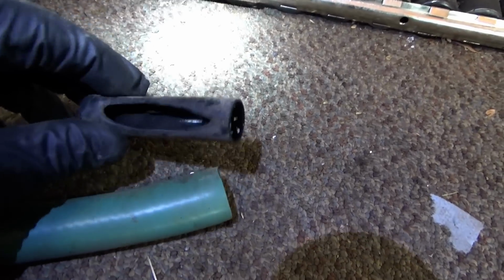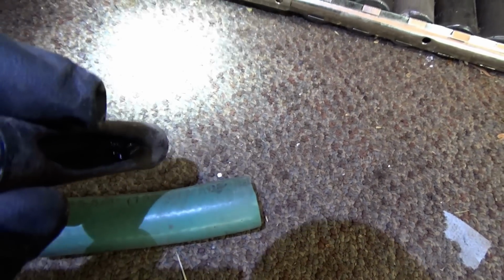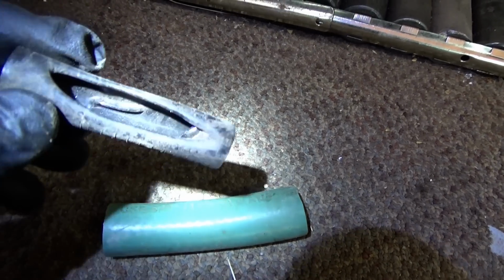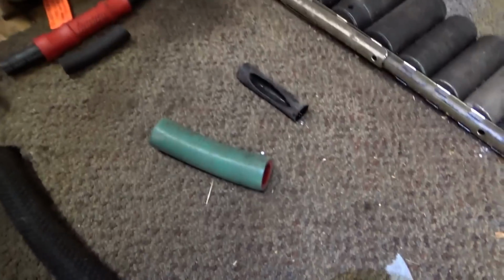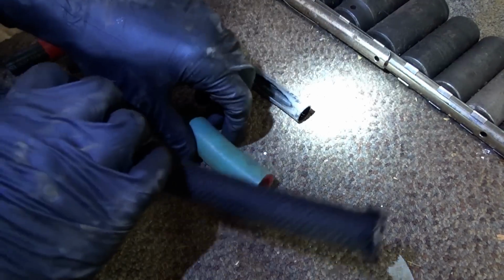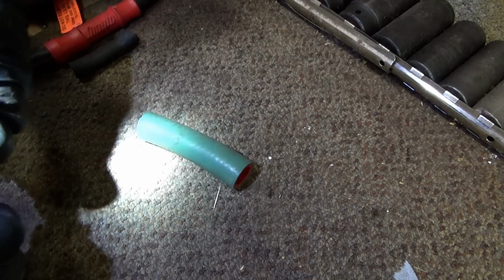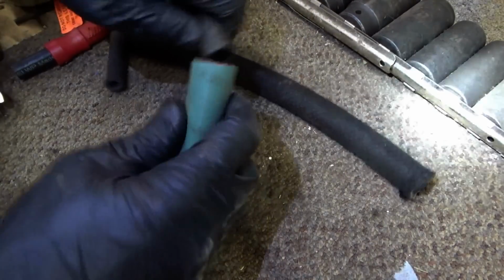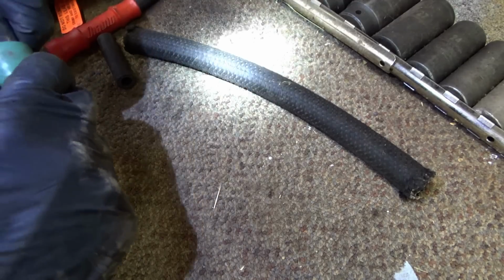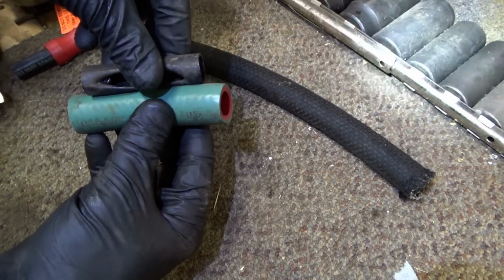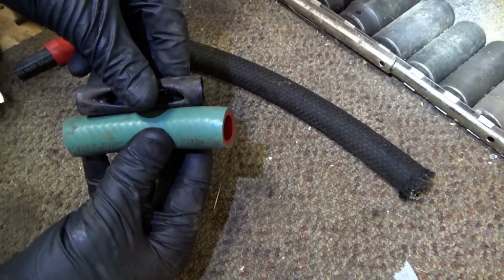This will be a nice little souvenir for the owner. That's why you couldn't fill your tank, dude. Your exhaust just melted your vent pipe. Wow, I don't think I've ever seen that before. Customer complaint confirmed. So now I have fuel-stable hose and this is silicone, so whatever is easier to fit. Silicone is probably a little more stretchy. Oh yeah, that's gonna work perfect. So let me just install this on that vent pipe, and we'll put everything back together.